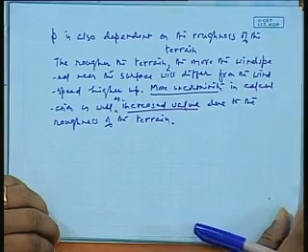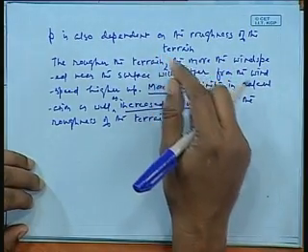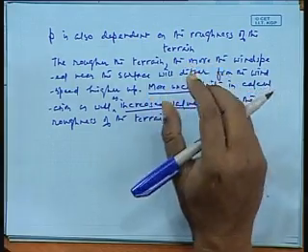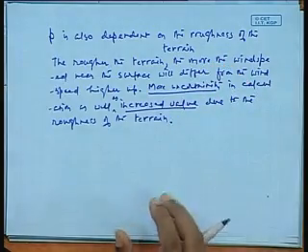So if it is just to explain it here, why I have come with this expression here, this power function, is only to suggest one thing, that in many cases in the calculation of the upper velocity at a height, about few hundred meters, if the velocity at the ground level is given, we can estimate the velocity at a higher level.